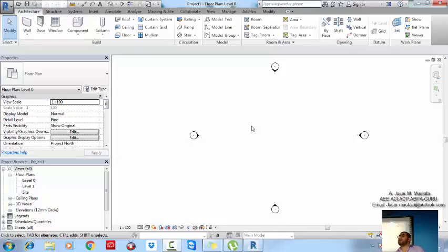Fine. Let's give a small example. When you are talking about Revit, it's like a huge bag, which is the program. This program is dealing with some families, and these families are broken down to types. So if you are using walls, the families that you are using are the walls. If you are using a stone finished exterior wall, the type of the family is that thing. If you are using a gypsum board wall, the type is the gypsum board wall, and so on.